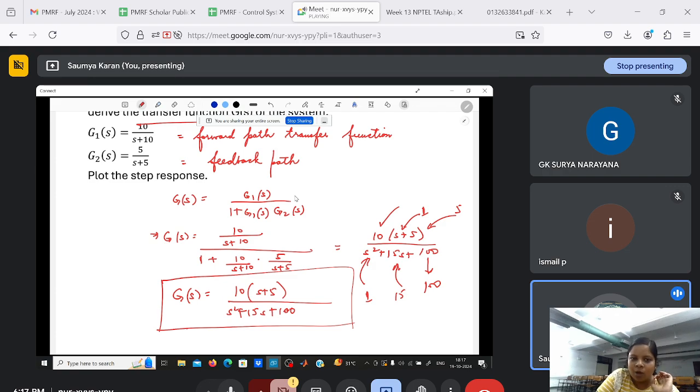Okay. Once you have the transfer function ready, figure is used to make a point that yes, I want to generate a figure right now. Step 2, G. G is my closed loop transfer function. If you call the function step on G, it is going to plot the step response for you. Title is for the picture and grid is on.